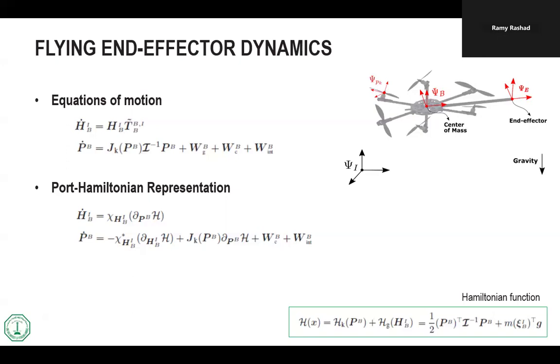If I take the gradient of the kinetic energy with respect to pi, I go back to Q dot. So there's some duality. Momentum and velocity are always dual to one another through this inertia matrix. This is no coincidence, always the case. Whenever you have any mechanical system, you can always go back and forth between momentum and generalized velocity using some inertia.